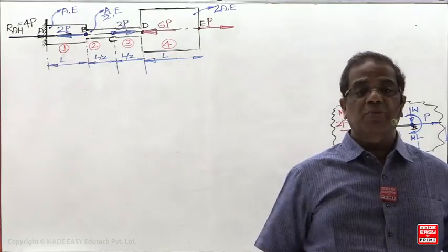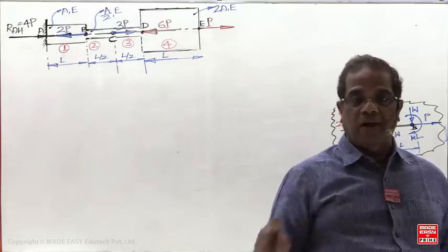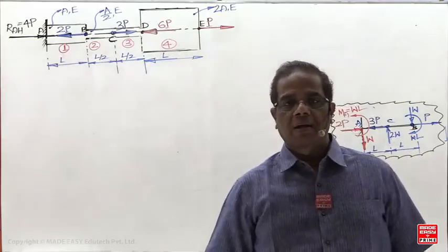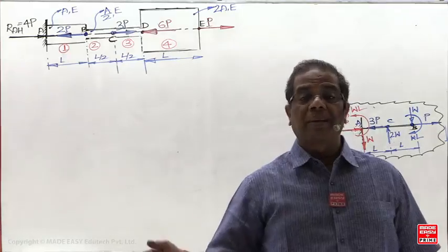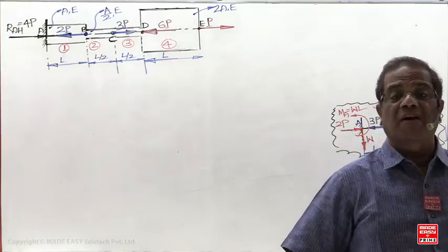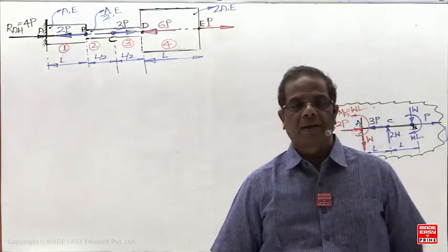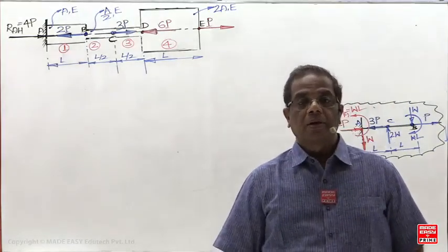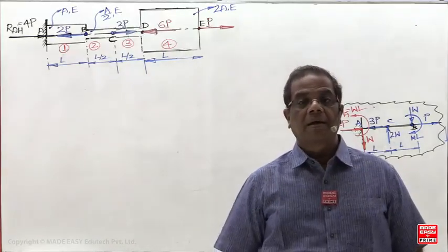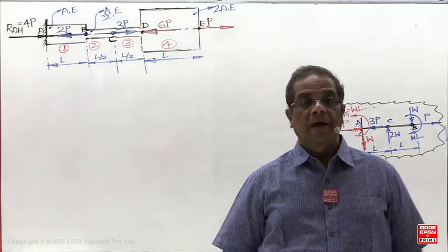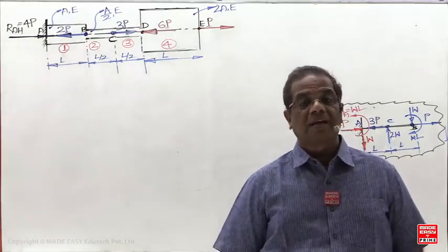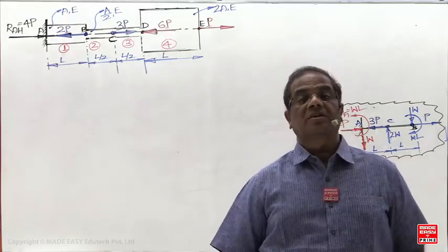What should be the first step for any question? The determination of the load. When you want to get the axial stress and change in length, the axial load is required. When you want to find the bending stress, the bending moment is required. When you want to find the torsional shear stress and angle of twist, the twisting moment is required. So how many ways can you find it? Four methods: the section method, the ALD, the free body diagram, and the shortcut method.